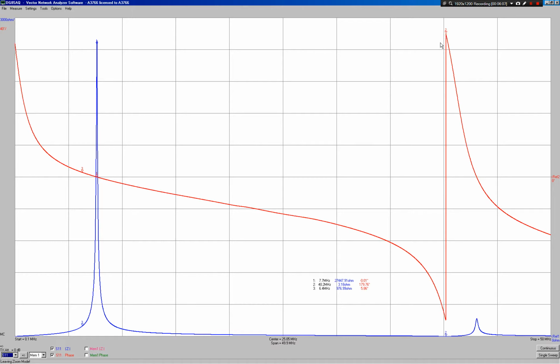And of course we've got this massive offset here with the parallel peak here, because we've got such a big imbalance between the inductive part of the reactance and the capacitive part of the reactance. So in that case, we see a very large offset between the parallel point and the series point. Obviously we have a secondary peak down here as well. That's quite normal for a self-resonating primary coil like this, and this is with 3 turns on it.